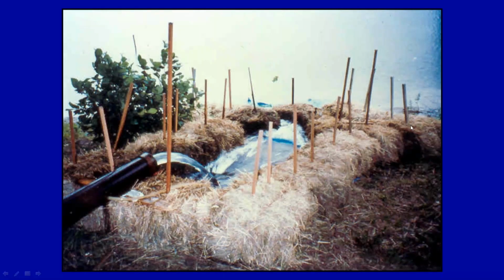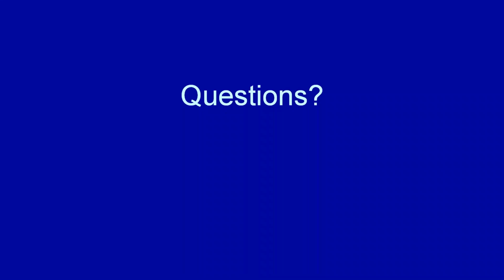Many times it's done by an orifice weir right at the point of discharge, where the weir will restrict the flow, causing in a tube on the side an elevation to come up, which is measured. There are tables that will predict exactly what the yield will be. Also, you want to be able to take the discharge water onto a sheet of plywood that we have jokingly called an energy dissipator, and keeping the Conservation Commission happy, surrounding it by sand hay bales so that there will be no erosion.